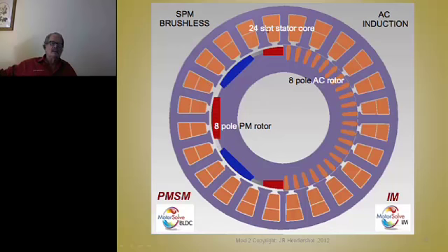It's called 24 slots divided by 3 phases is 8 coils or slots per phase. So if you got 8 poles, then 8 into 8 is 1. So it's 1 slot per pole per phase, or 1 coil per pole per phase. Okay, so that's how it's wound. Now, notice that the magnets are glued on there. They're locked in there. They can be dovetailed in, or they can't move. They don't slip. But we replaced that permanent magnet rotor with an induction rotor.